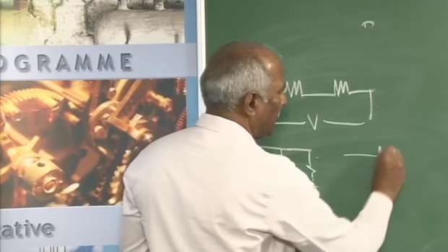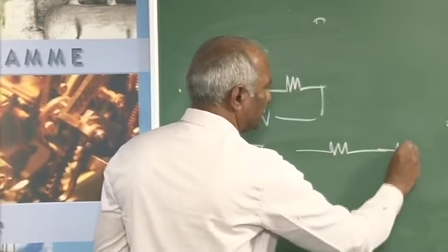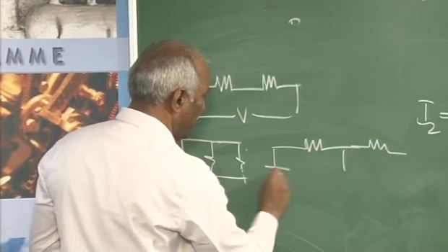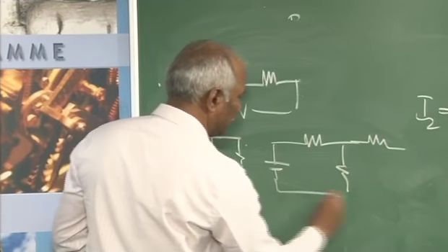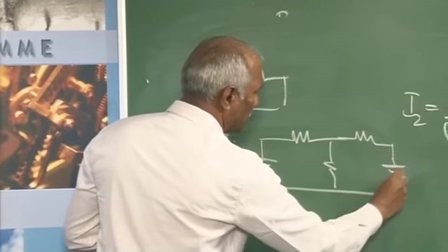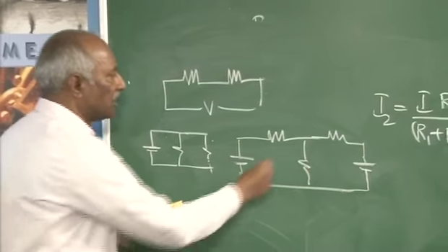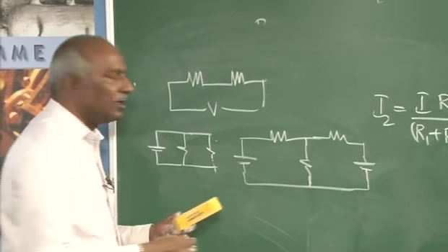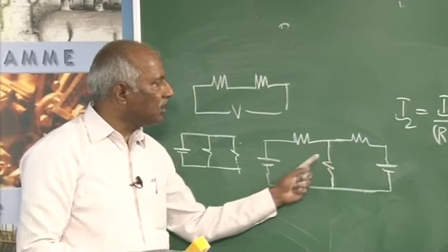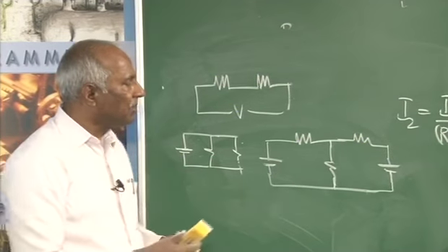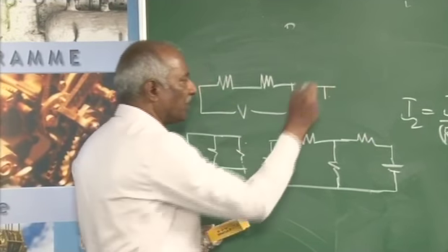However, when you have a circuit supplied by two sources and the resistances are connected in this way, they are neither in series nor in parallel, they are actually in what's called a T configuration.